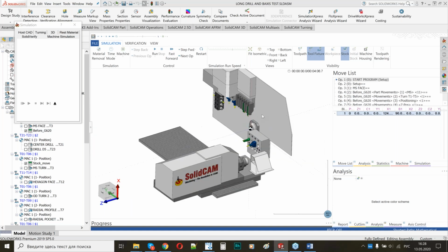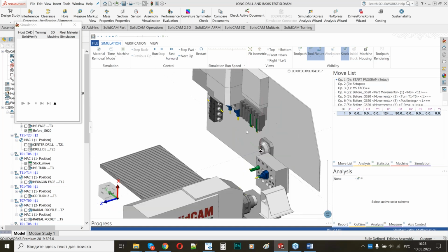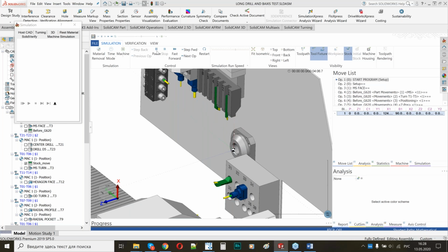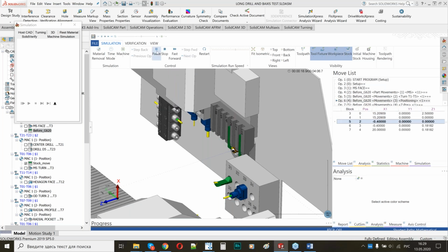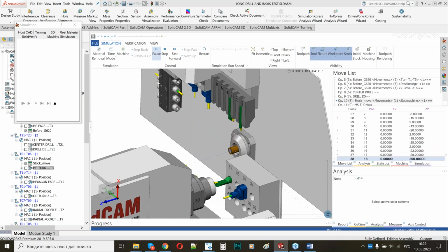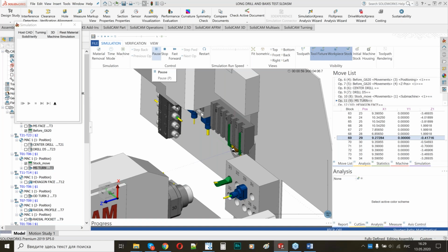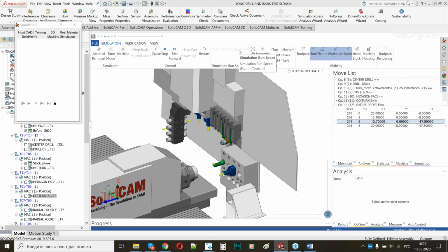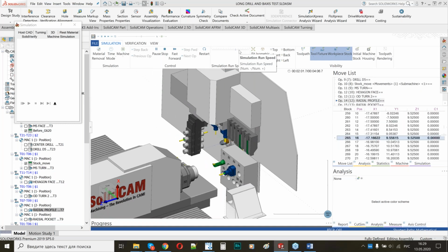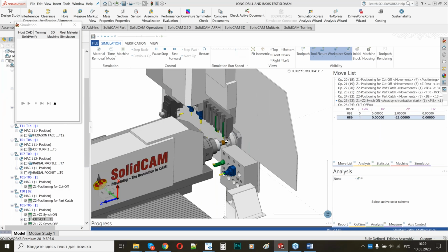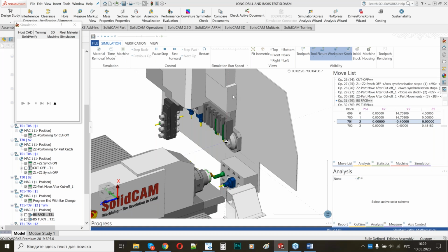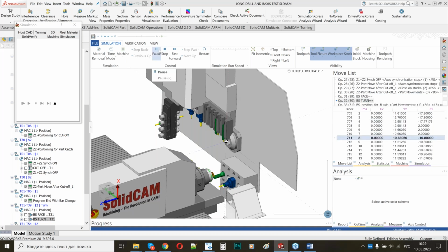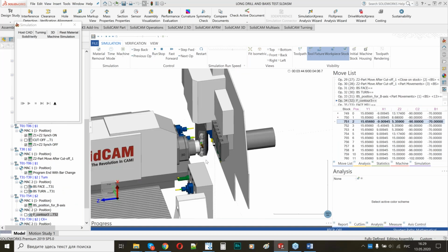Okay, so this is what we saw previously. It should be facing, then long drill, then turning again, milling, milling, turning, then milling again, radial milling, part transfer, turning, and then I will have my B-axis operation on a back spindle. So this is what I have here.